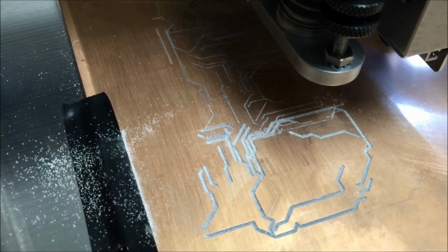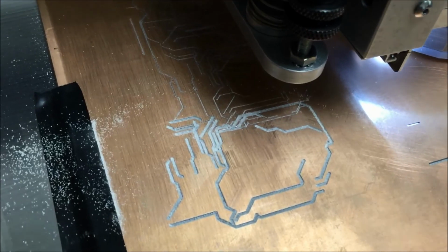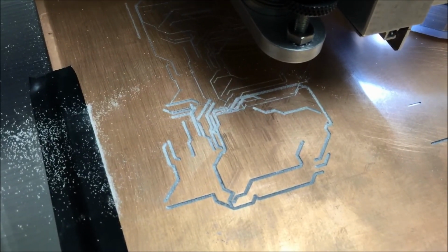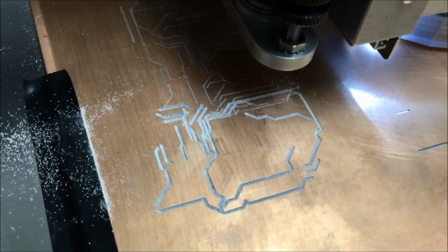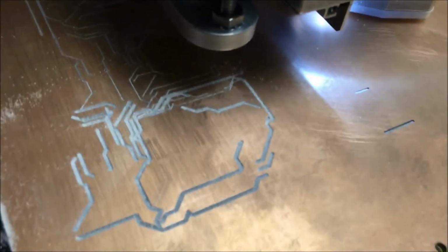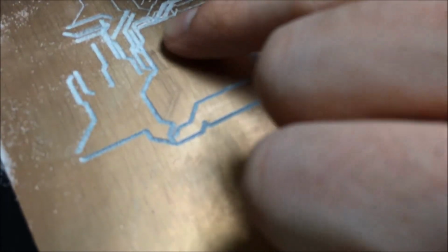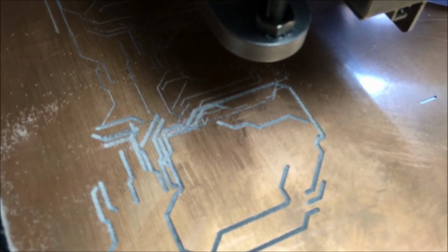Now, it called for a 10 mil tool, and this tool is actually 12 mils. Again, I just wanted to display the full functionality here. But you told it was 10 mils, even though it's 12. Yeah, so it thought it was 10 mils, so that can explain some of the overrunning, like over here, I think. Maybe it is going a little bit too deep or the traces are a little bit too tight. But again, you really got to do your due diligence if you're making a board on this.